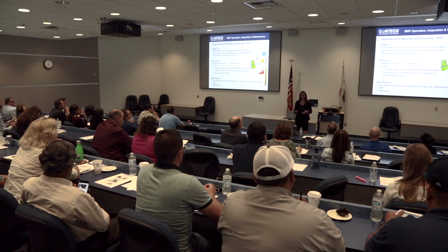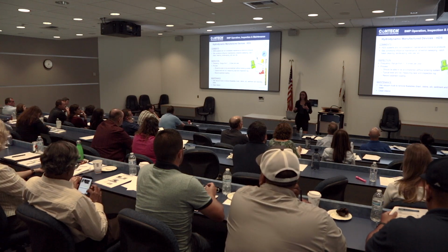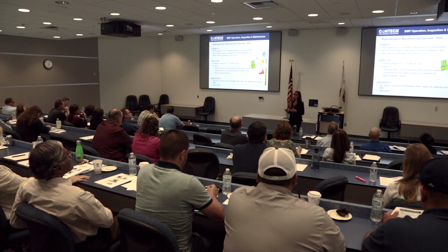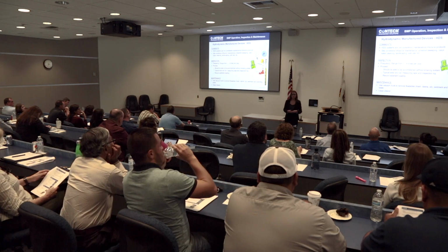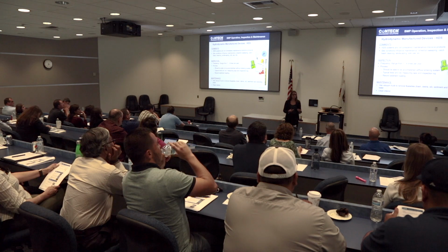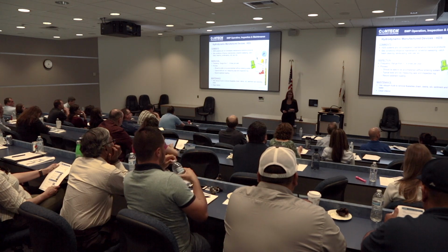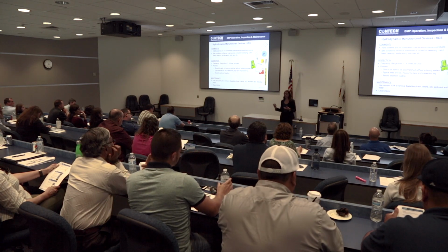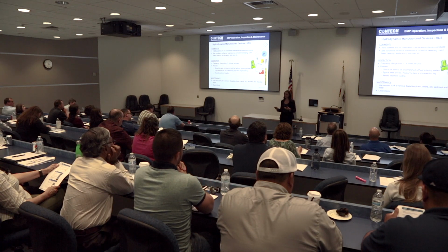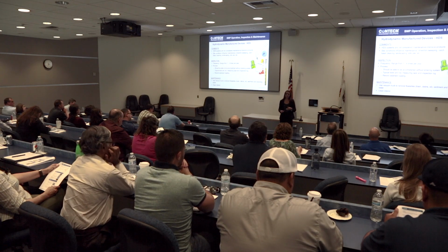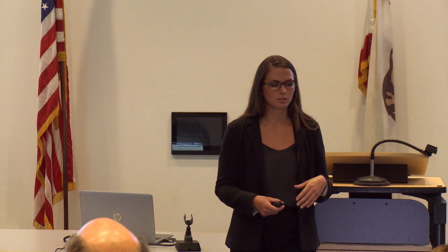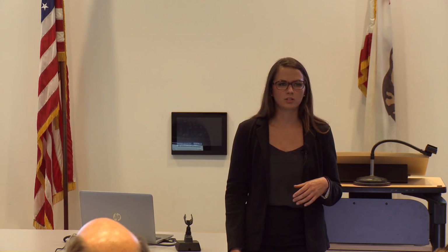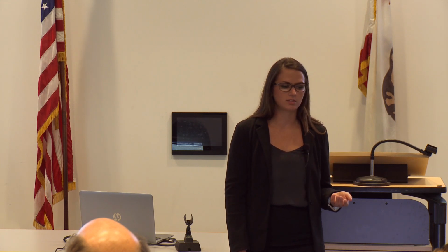At this time, I'd like to talk a little bit about the maintenance of our pre-treatment or filtration systems, starting off with hydrodynamic separators. HDS or hydrodynamic separator systems are not seen as maintenance-intensive products. However, the amount of maintenance can often depend on the site conditions the product is in. For inspection, we recommend that you inspect 1 to 4 times a year. The process could be accomplished without entering the system.